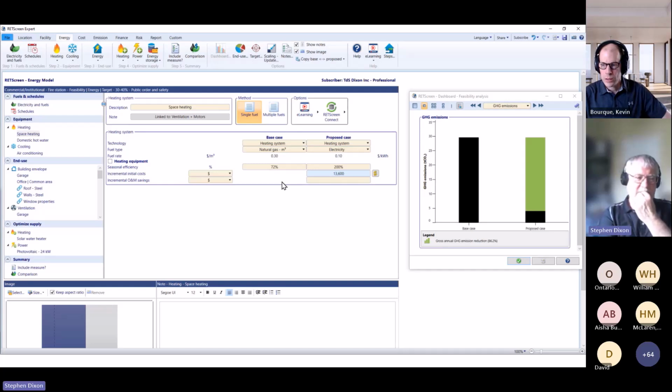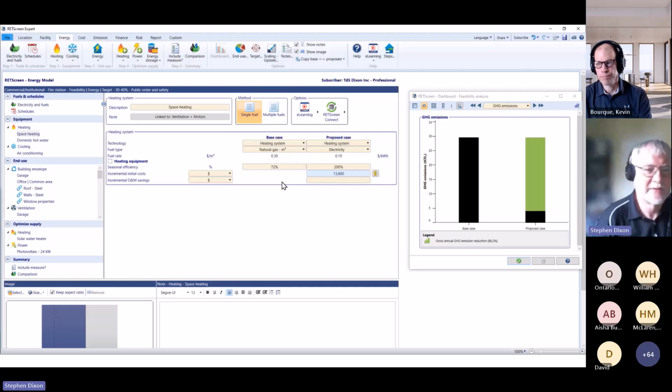So if somebody says the COP of the heat pump is 2, then the efficiency is 200%. Now, the seasonal efficiency corresponds to the seasonal COP, and the seasonal COP is over the course of the heating season. It's not just an instantaneous maximum value, it's over the course of the heating season. In a gas furnace, you often see on the side of it AFUE, annual fuel utilization efficiency, and that's the closest thing you can pull off a label to the seasonal efficiency of that device.